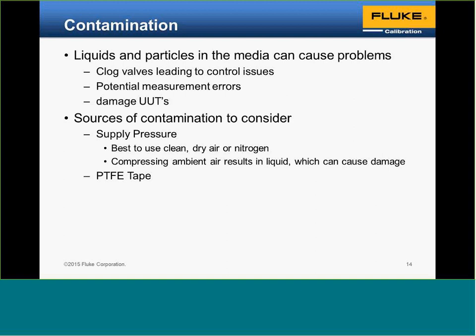Two wraps are necessary, and that's it. With the fitting, make sure you're wrapping in the proper direction, and leave the first thread blank, because that first thread is what gets cut off when you're putting the fitting into the system, and that part will get clogged into valves and so forth.